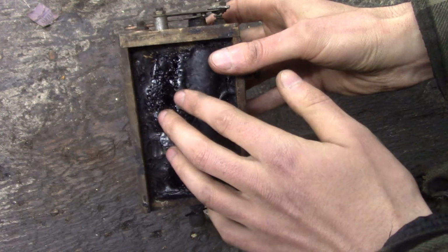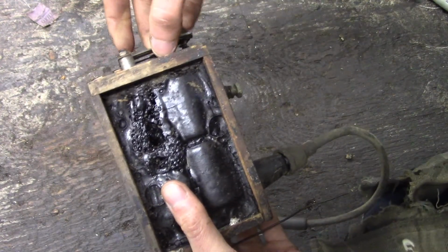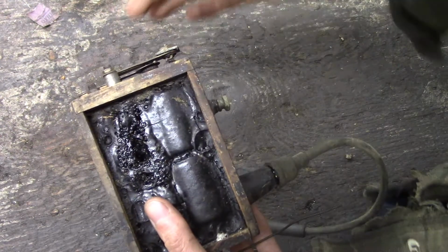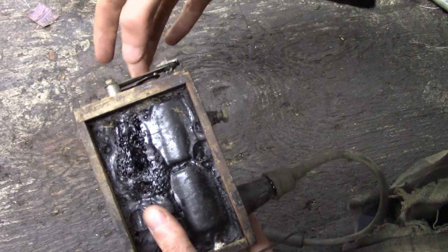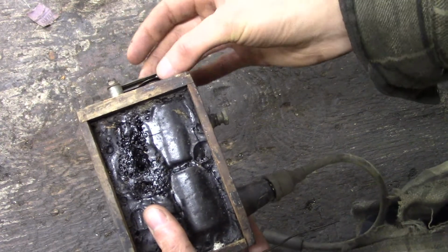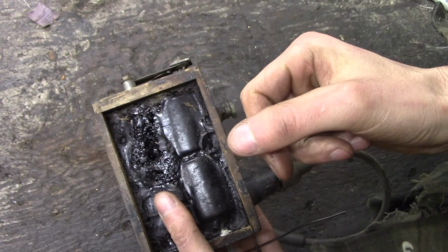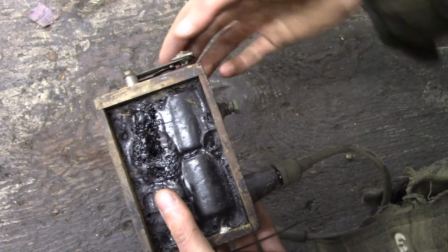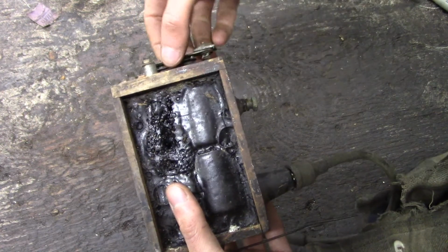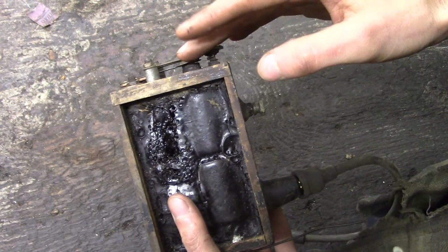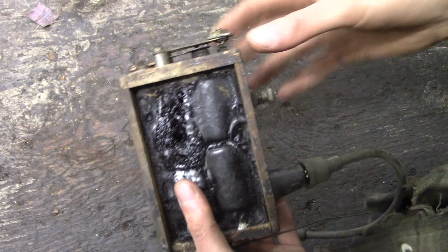And the condenser is needed, this is the extent of my knowledge, but it has something to do with balancing the voltage on either side of these points, so the points don't wear out like they would in a low tension ignition application. So with a condenser, you can make these points last a lot longer because it won't spark across the points when they make and break contact to the primary coil.